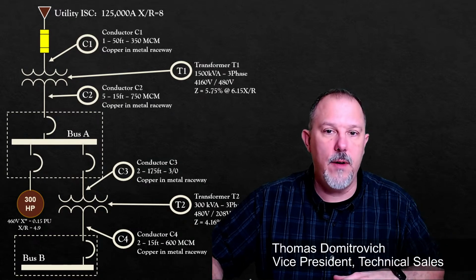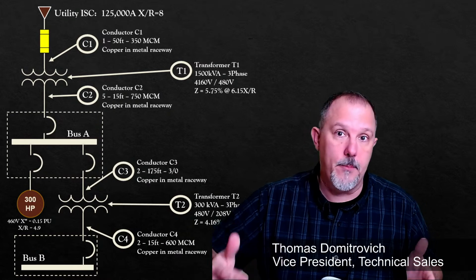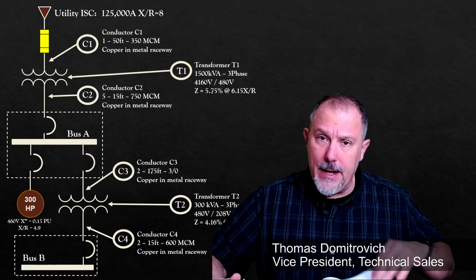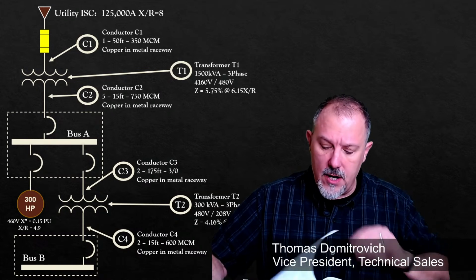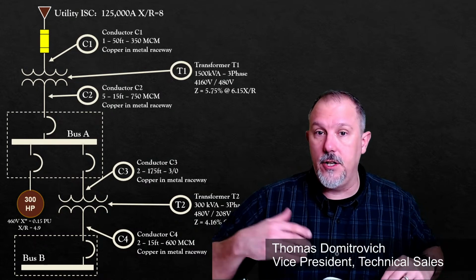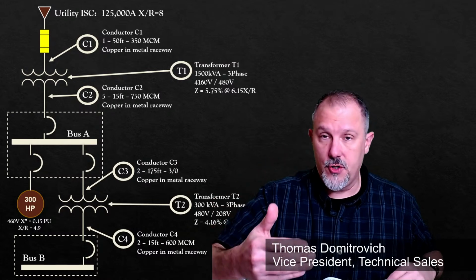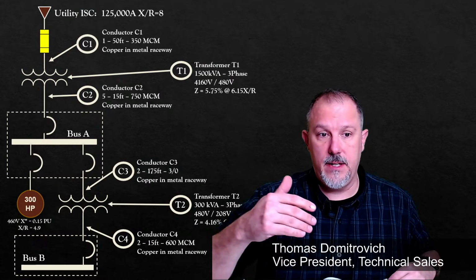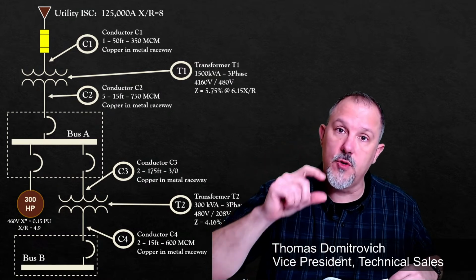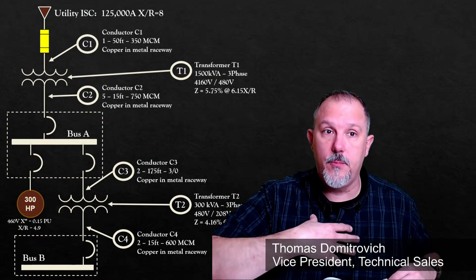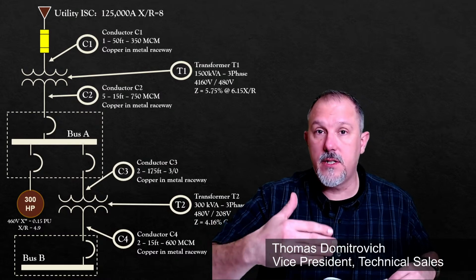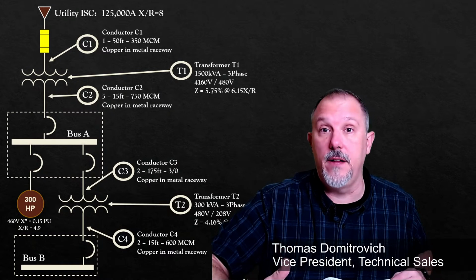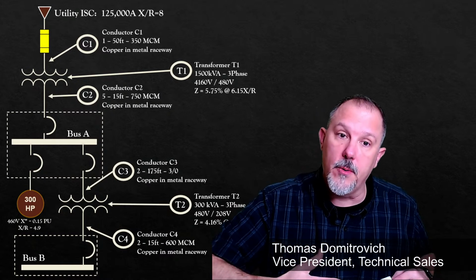I'm not going to go at full load amps because I'll trip that breaker every time I energize it. So in reality, we'll start off with 1.25, and I know Eaton has a paper that says we're trying to design our transformers so that you can use 1.25. That gets you into a smaller breaker.